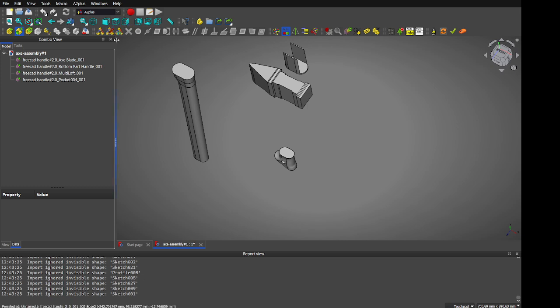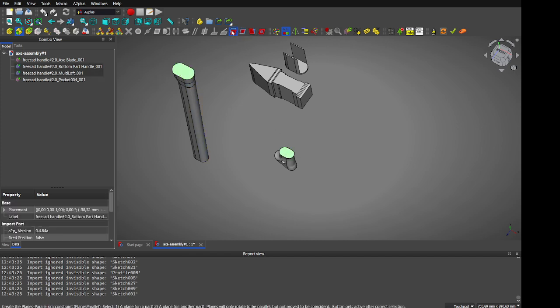The way in which A2plus works is you select one surface and then select another surface, and you can use constraints. By these constraints you are making a consistent shape. Consistent shape means this shape isn't able to be dissolved into smaller pieces, so it acts like one part connected by adhesive.